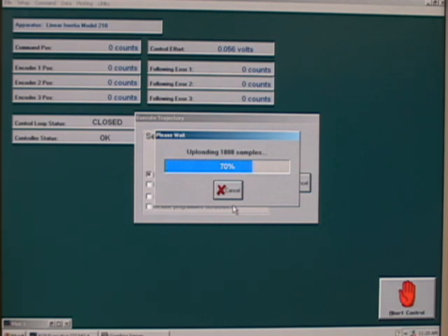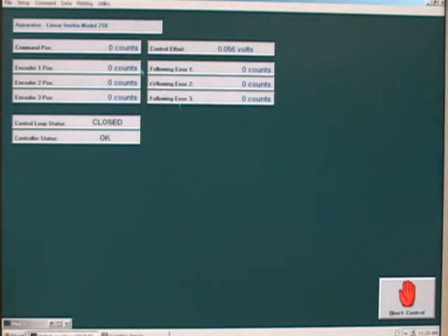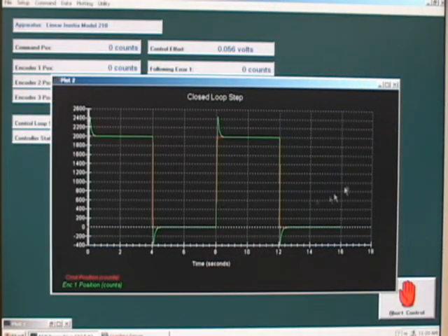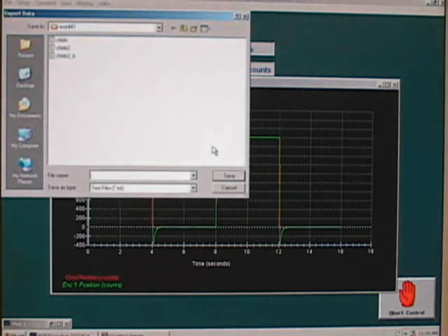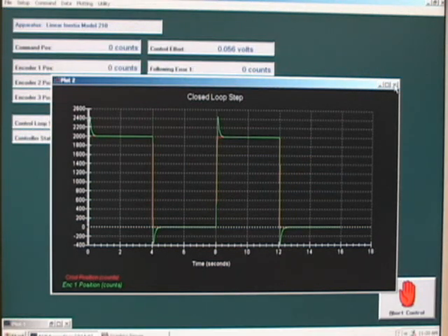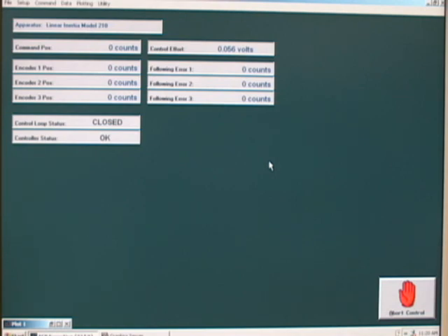We will quickly show then how to plot that via the plotting, setup plot, plot data, and we see that this looks consistent with the MATLAB program, PID. We can export that raw data, again, probably to the Z drive somewhere, and you're then ready to change those data files and then get those in the working directory of MATLAB and execute PLT3 to analyze that hardware data that you've now collected. That should finish up then lab number 3.